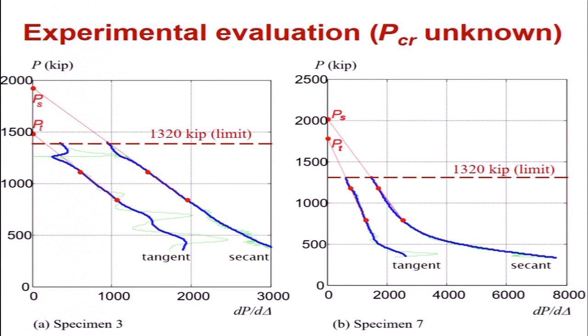rather well, okay? Typically, when you start a test, there's a lot of noise down here. So you really need to pick a couple of points. And I said, again, we picked 60 and 80% of the ultimate value sort of arbitrarily because most of those points tended to fall in a fairly linear range of these plots.